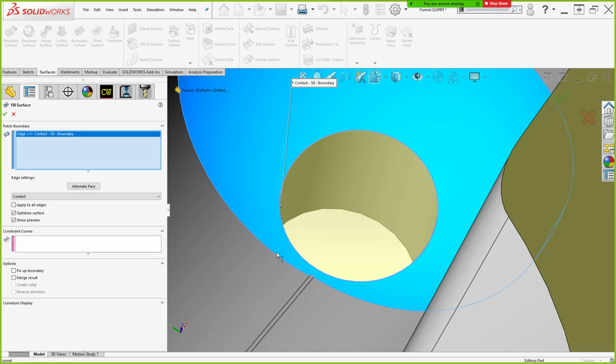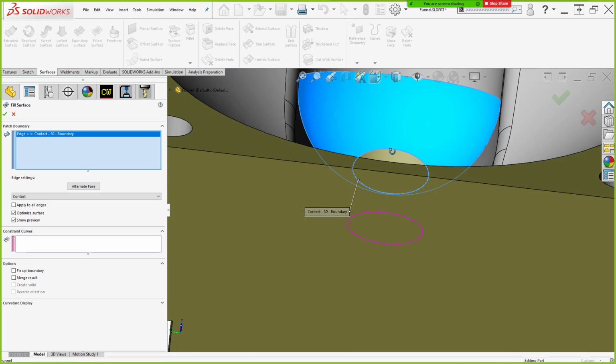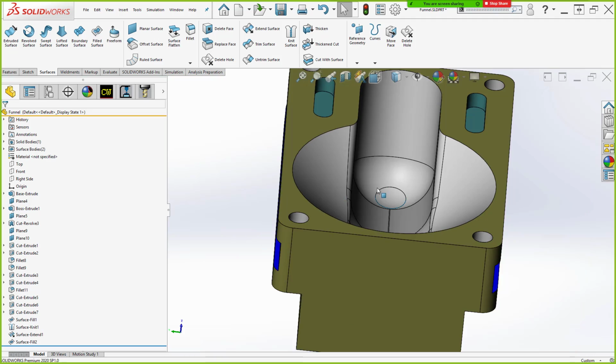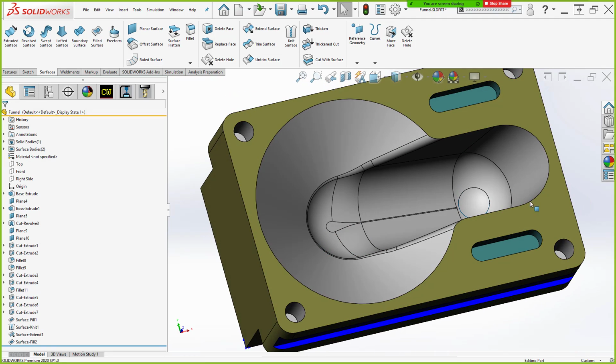It's just a very straight shape. So it might not give you the best toolpath. You want your toolpath to come down nice and arcing and sweeping and continue sweep. You don't want it to go arc, arc, arc, arc, straight line, arc, arc, arc, arc, right? You want continuous. So you can bump up the quality of this guy, tangent or curvature. Curvature is the best quality. Tangent is usually more than enough, 99.9999% of the time, especially when it comes to CAM. So I go with tangent.